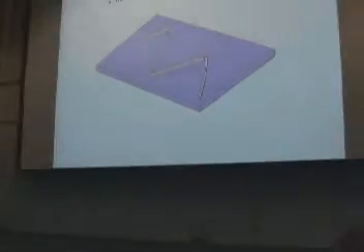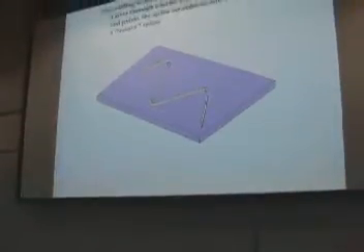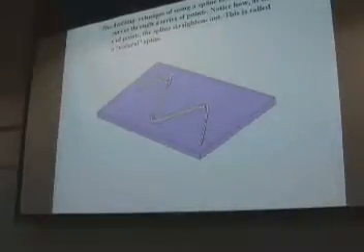Practically, in drafting technique, they use a spline to draw a smooth curve through a series of points, as you can see here, different points. At different intervals, you use a spline to do the curve fitting. And notice that at the end point, the spline straightens out, and the second derivative at the end point is 0. That is called a natural spline.